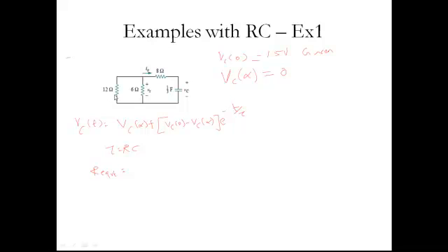You can see 12 ohms and 6 ohms are in parallel. That combination is in series with 8 ohms. Okay, so you can write 12 into 6 divided by 12 plus 6, plus 8, which will give you 12 ohms. So tau is nothing but 12 ohms into the capacitance value of 1 by 3. So tau is equal to 4 seconds. Substitute all these values here. Vc of infinity is 0, Vc of 0 is 15, Vc of infinity is 0, e power minus t by 4. So Vc of t is nothing but 15 e power minus t divided by 4.